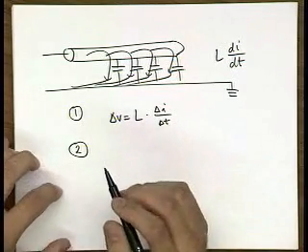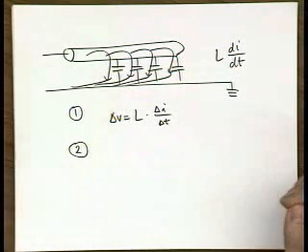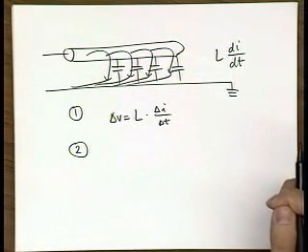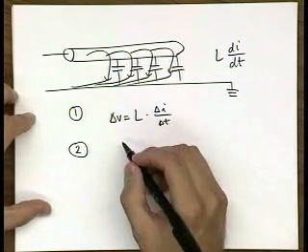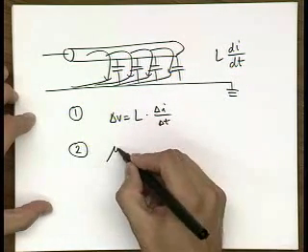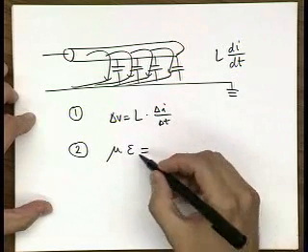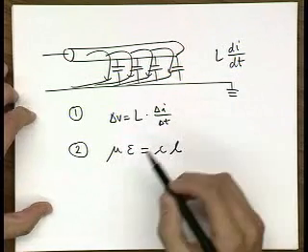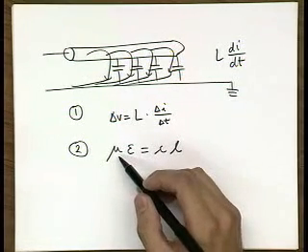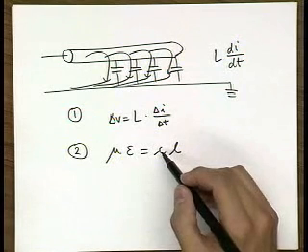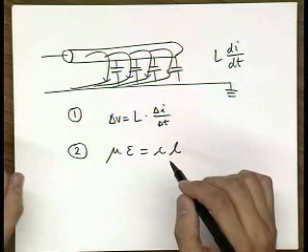So it is really hard to estimate the inductance of a single isolated wire. The second approach is that you can utilize the properties of the environment of a wire, its geometry and certain dielectric constants. So you have this expression, which you probably have seen in your EM classes or physics classes: the product of dielectric permittivity and permeability is equal to the product of capacitance per unit length and inductance per unit length.